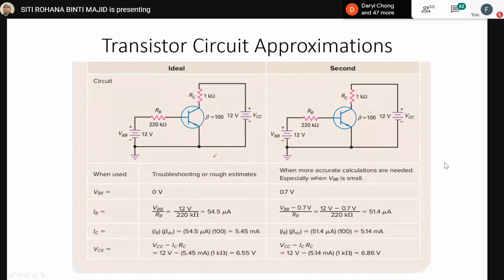When there are two crowds of charge carriers, the collector current will sharply increase even though you change a very small value of VCE. Too many charge carriers, and at the same time you should be aware that the base is very thin, the thinnest layer among the three layers.